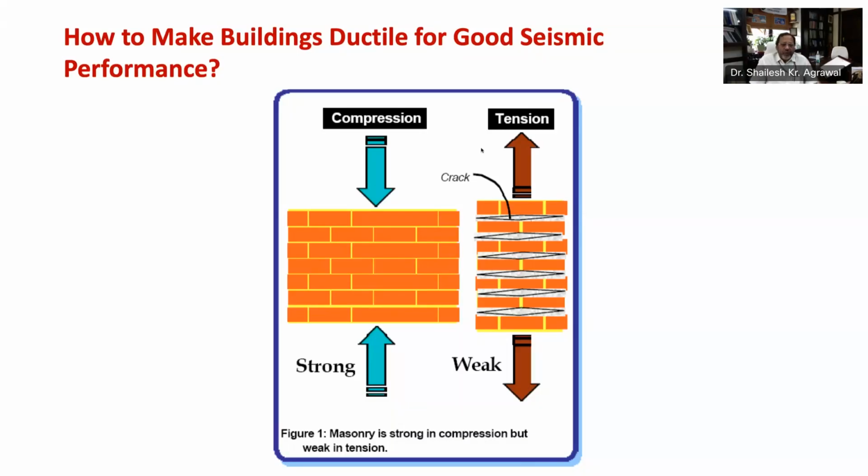Concrete is therefore used in buildings along with reinforcement bars. This composite material is called reinforced cement concrete or simply reinforced concrete, RCC or RC. This is the most prevalent construction material being used the world over. However, please note, for earthquake resistant construction, the amount and location of steel in structural member should be such that the failure of the member is by steel reaching its strength in tension before concrete reaches its strength in compression.